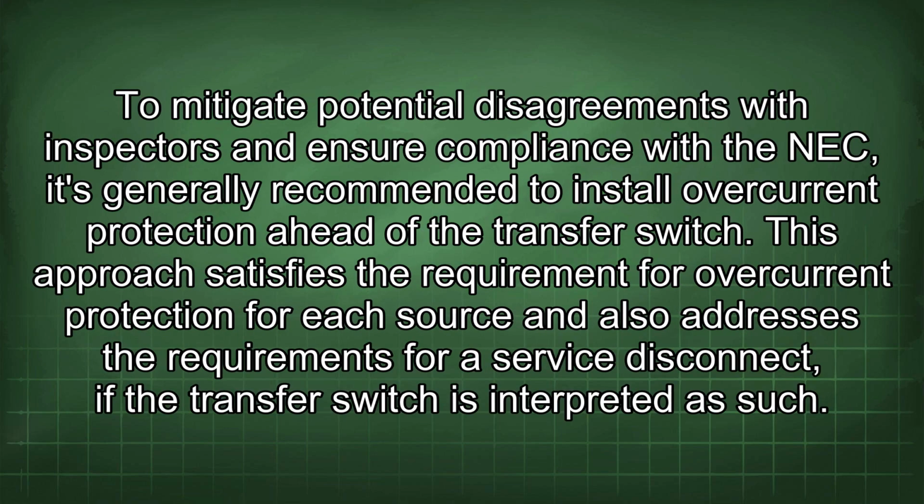To mitigate potential disagreements with inspectors and ensure compliance with the NEC, it's generally recommended to install overcurrent protection ahead of the transfer switch. This approach satisfies the requirement for overcurrent protection for each source and also addresses the requirements for service disconnect if the transfer switch is interpreted as such.